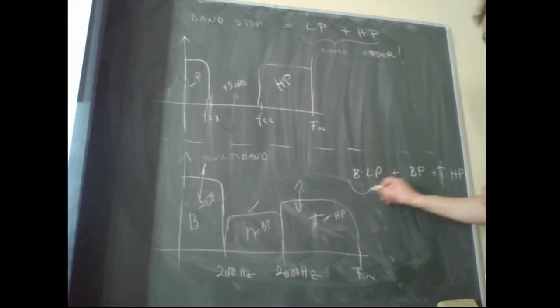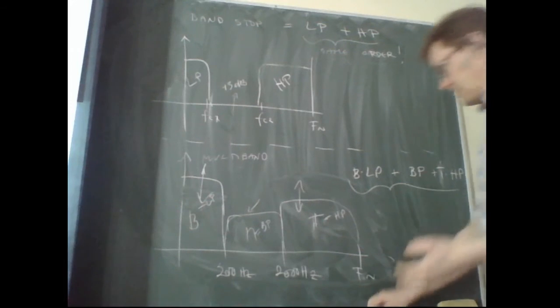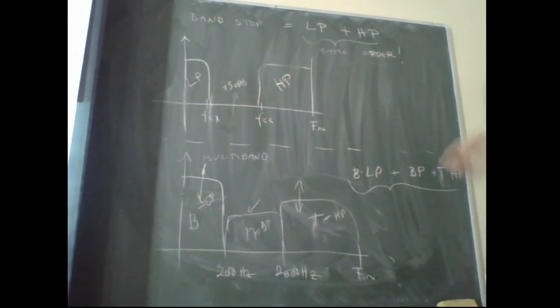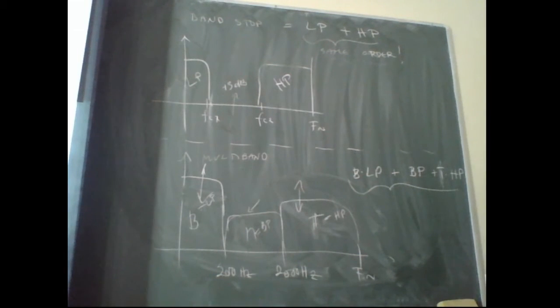So you calculate these coefficients and just have one single filter implementation for the data. Okay. But in IIR, you practically have to make 3 different filter implementations. So, yeah, that's maybe another reason to work with the FIR systems.